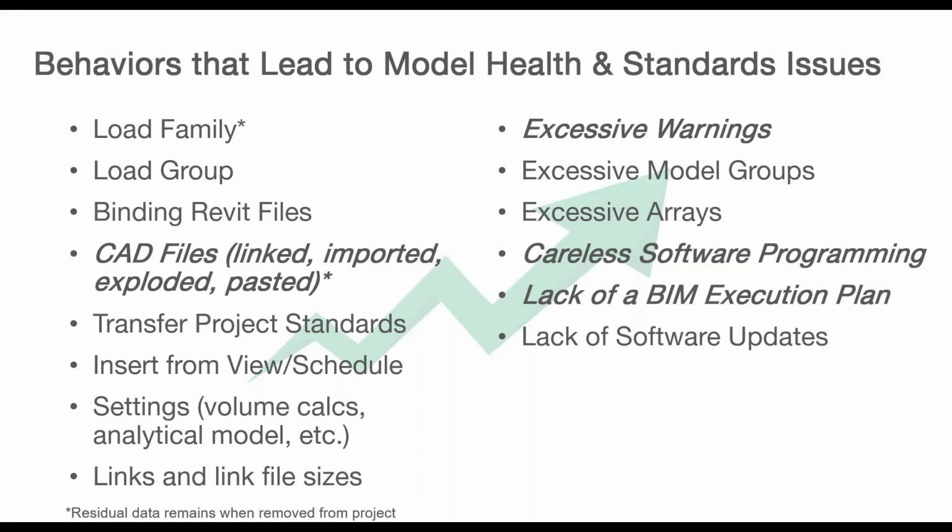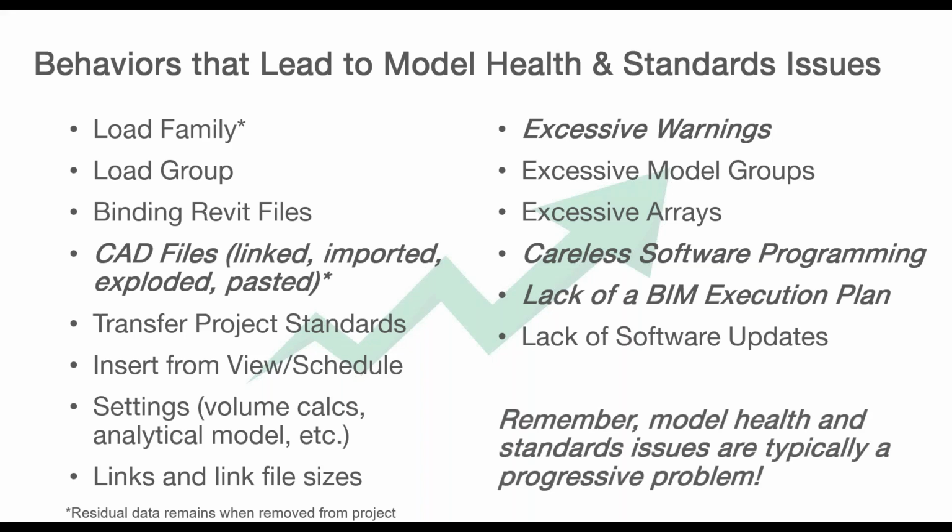All this really leads to a good BIM execution plan. I cannot stress the importance of having a solid BIM execution plan. Get that in place, have a plan for cleaning up your models for both standards and health issues. And remember, model health is typically a progressive problem. These are things that creep up on you over time.